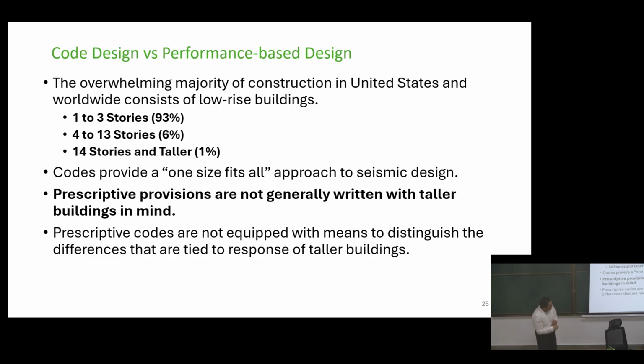And prescriptive codes are not equipped with means to distinguish differences that are tied to the response of taller buildings, as I said, higher mode effects and dynamic shear amplification, which are two very known phenomena for taller buildings.